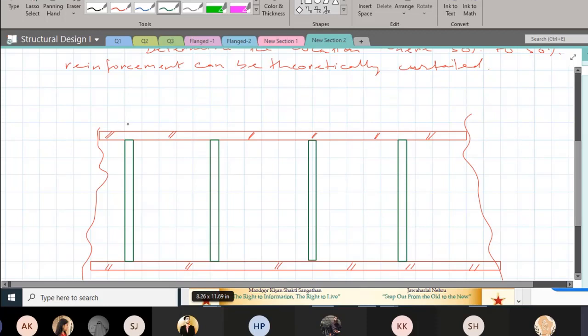By 3 meters center to center, I mean here the center line of the beam. So this distance is 3 meters, this distance is 3 meters. It is like this. This is the problem which has been given, and it has also been said that at any one of the intermediate beams, say this is the intermediate beam, over this beam you have a wall carrying a load of 12 kilonewton per meter.